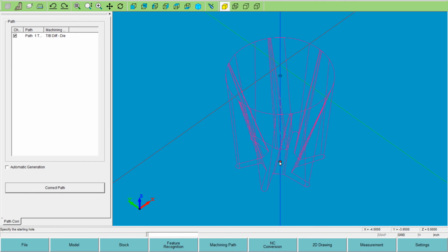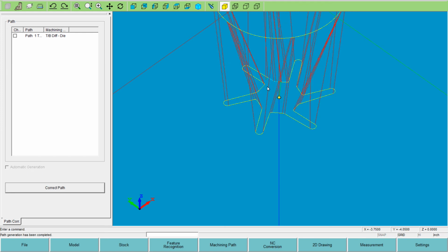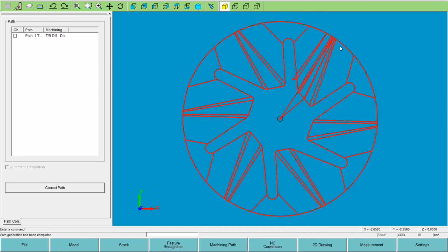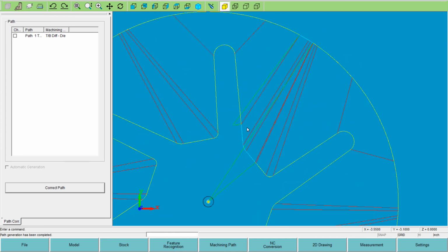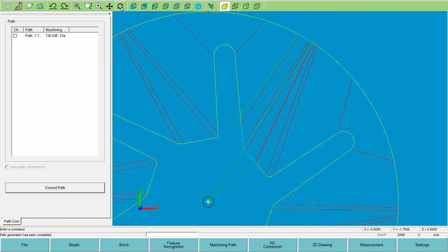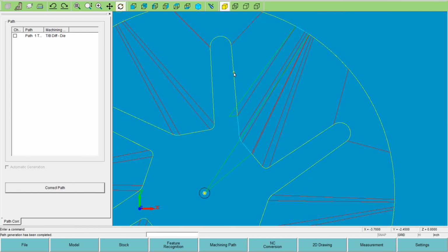Shut that off. There's my start point. Didn't get the message, right? So let's see where we put it. It's way back over here, at a 1/2 inch back. Now I got it away from all this other geometry so that you can see what's going on. Here's your hold on tab of a 1/2 inch, but the reference plane on the bottom is your 1/2 inch distance. And let's tip it a little bit so we can see what's going on.